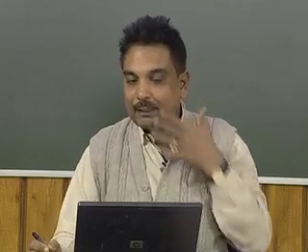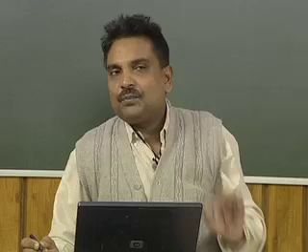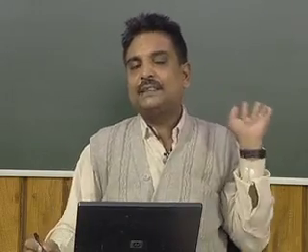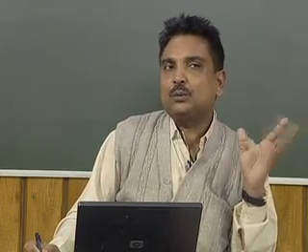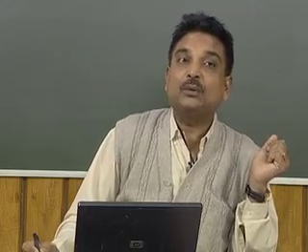Now, after we get the value of local temperature, for part C we again have to find the value of Q by Qi. From the figure we have to find this versus Biot square into Fourier. All the values are known to you, Biot square into Fourier is exactly the same as we have done for the previous case. I have intentionally taken up this problem just to illustrate this for 3 different geometries, and the differences lie in consulting the charts and getting the values of the different parameters required by the problem.